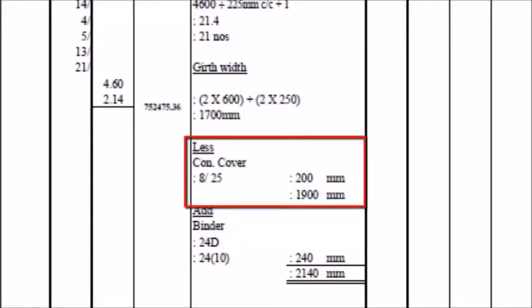The concrete cover is calculated for each side of the edge of the girth inside the ground beam. Each edge, we have 1 horizontal side and 1 vertical side. Now, a square will have 4 edges multiplied by 2 sides. So, the amount of concrete cover is 8. As inside the British Standard, the size of a concrete cover is 25 mm. So now we multiply 8 by 25 mm in order to get the total amount of concrete cover that needs to be less in the calculation.